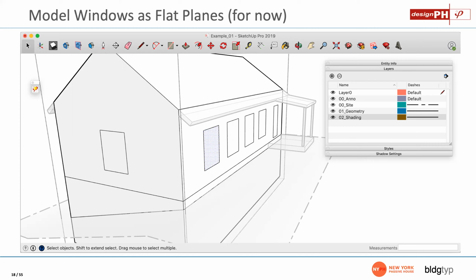The convention in Passive House land is to use what we call exterior dimensions. That is, we're going to measure to the exterior surface of the building. That won't always be the case. It sort of depends on how you built your U values, if that actually makes any sense. If you took the vented cavity into consideration when building your U values and the cladding, then you would just draw to the edge of the cladding. If not, you would draw to the edge of the insulation if you're doing continuous exterior insulation. So it sort of depends on where you drew your edge of your U value.